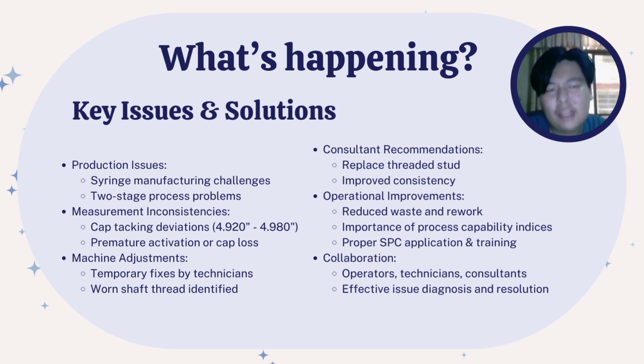Consultants found that the shaft thread was excessively worn, causing inconsistent cap tacking. Adjusting the stop upward allowed the lock nut to secure better, resulting in consistent but slightly longer syringes. The consultants recommended replacing the threaded stud, which significantly reduced waste and rework.